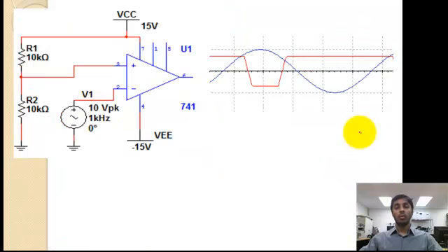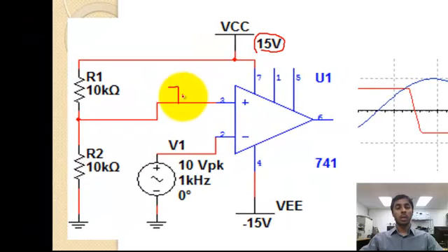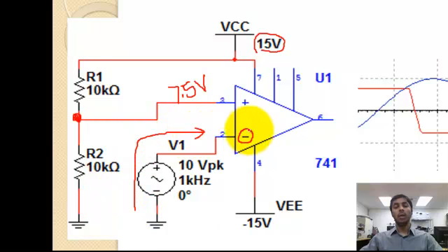If you reverse the inputs, as we saw before at the zero level detector, it's still 15 volts, a positive voltage. So 7.5 volts is connected to the V positive because that's where it is coming off of from a voltage divider network, and the input signal is applied to the inverting terminal. Remember, if an input signal is applied to an inverting terminal, the input signal and the output signal are going to be out of phase by 180 degrees, and you can clearly observe